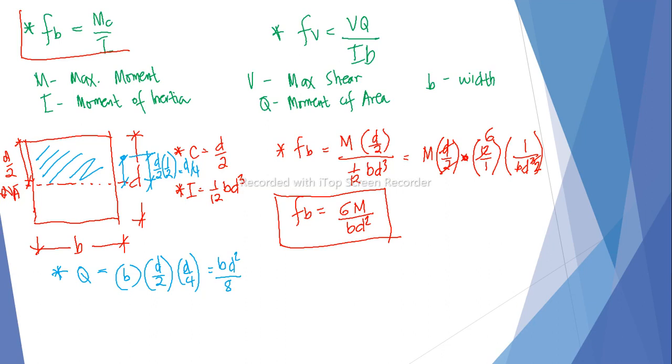I think there is nothing new here. Then we solve for our shearing stress, which is equal to V times Q, which is BD squared over 8, over IB.